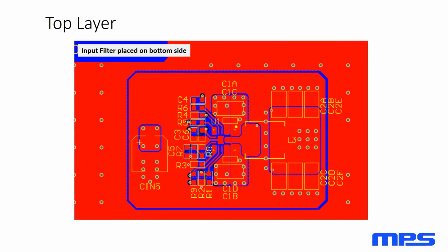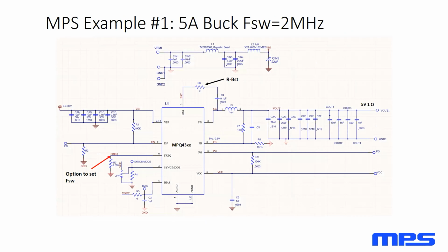Typically, go back to the full schematic here. What you're going to see, so these are like 1 nano, 10 nano, these are 0603s, but a 2.2, we don't have the case sizes listed there, but these particular components will be larger based on the voltage rating of the capacitor. Typically, the larger the parts, the larger the voltage rating possible, and the larger the capacitance as well.